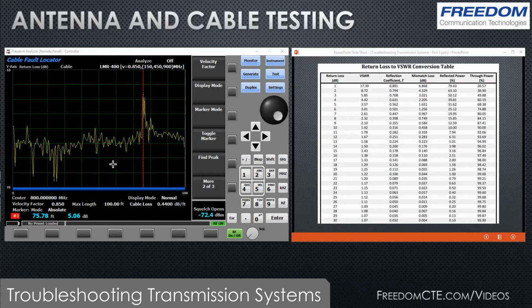Here we have it. So now I have the portable antenna hooked up to the end, and you can see that at, again, a little over 75 feet, I'm looking at a little over 5 dB of return loss. Again, we'd expect about 6 dB, but this antenna is not mounted to a radio. There's no good ground plane, so it's not quite as good a performance as you can get with a portable antenna. Again, 6 dB for a portable, 14 dB minimum for a base station antenna.